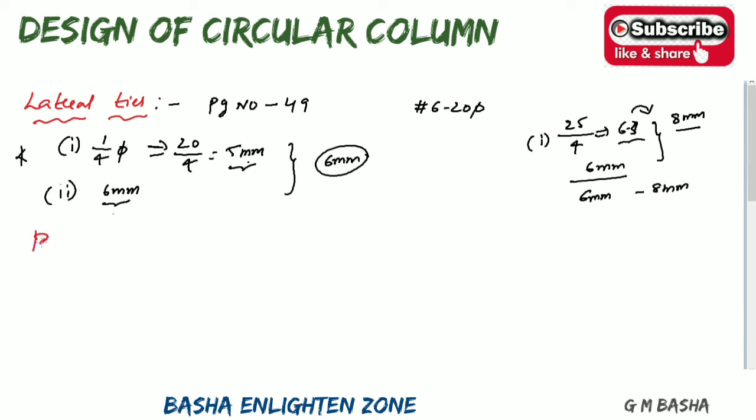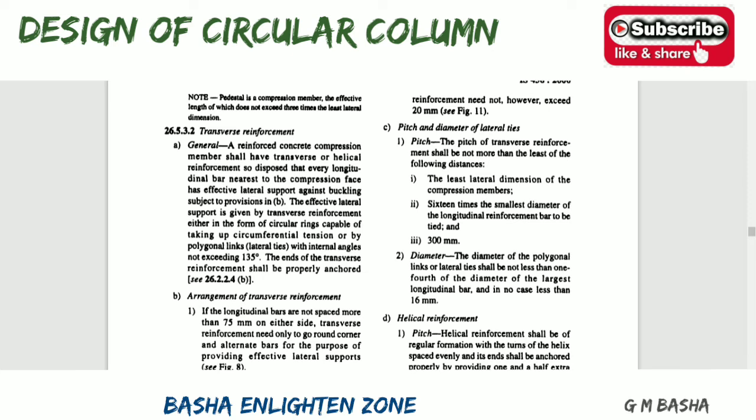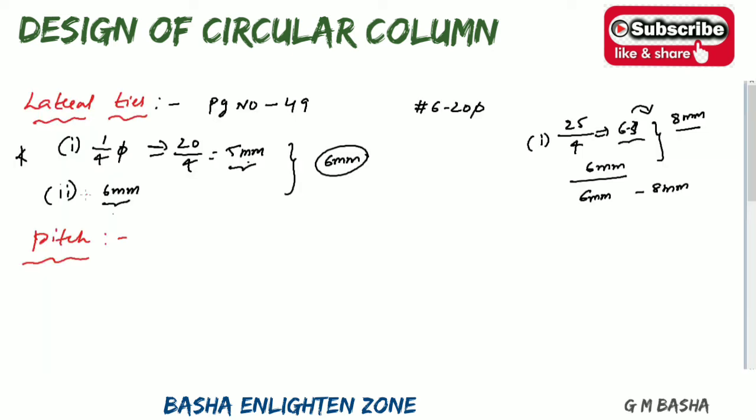Then the next condition is pitch. Pitch is what we call spacing in beams; in columns it is called pitch. For pitch there are three conditions. First, the least lateral dimension of the compression member. For example, if we are solving a square column of 420 by 420, both dimensions are equal, so you can take either value.